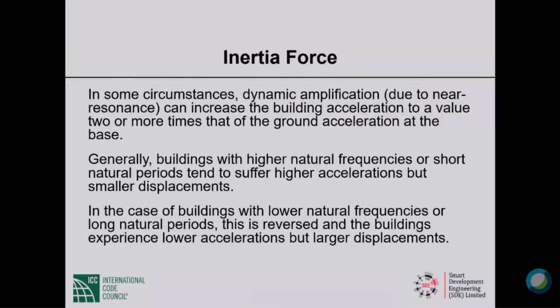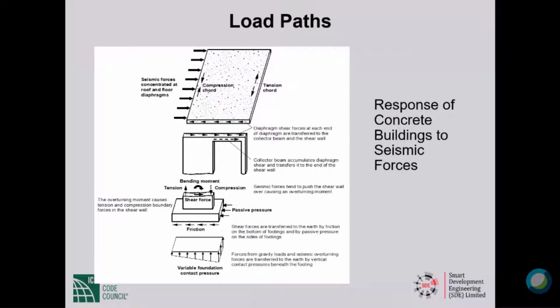So we are dealing with inertia forces at the floor slabs and the roof, where the masses are largely concentrated. We are looking at the roof slab of a building. It is subject to inertia forces from left to right because the foundation underneath is moving from right to left. Those inertia forces cause in-plane bending of the roof slab. So in that case, the roof slab is acting as a diaphragm, as we call it.